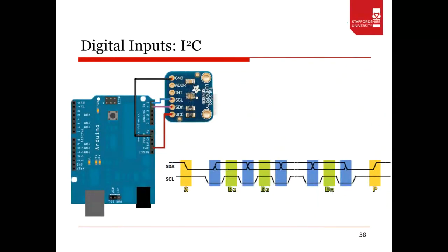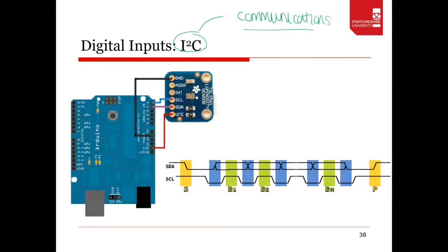Here we have what's known as I2C. I2C is a communication protocol that we're going to be looking into a little bit more in these lectures. I would like you to read around at what I2C is. The good thing about it is it only requires 2 wires.